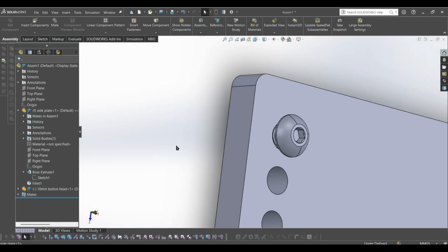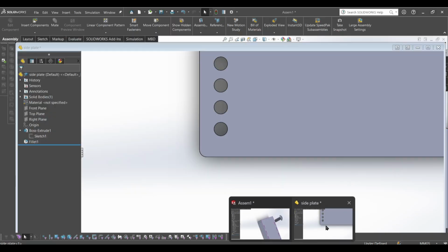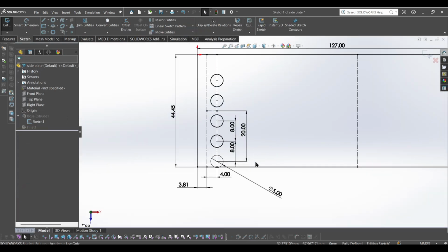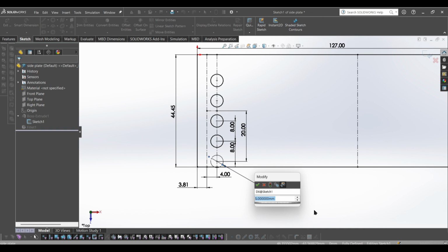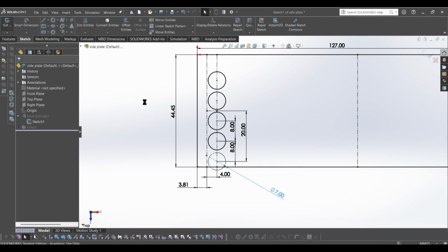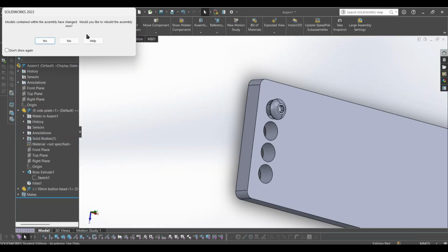And you need to make sure that you don't tolerance by way too much, because if you do that, then the part won't be able to do its function. So for example, if I tolerance this by 3 millimeters and I made it 7, then it starts to get a little bit wonky for 2 reasons.